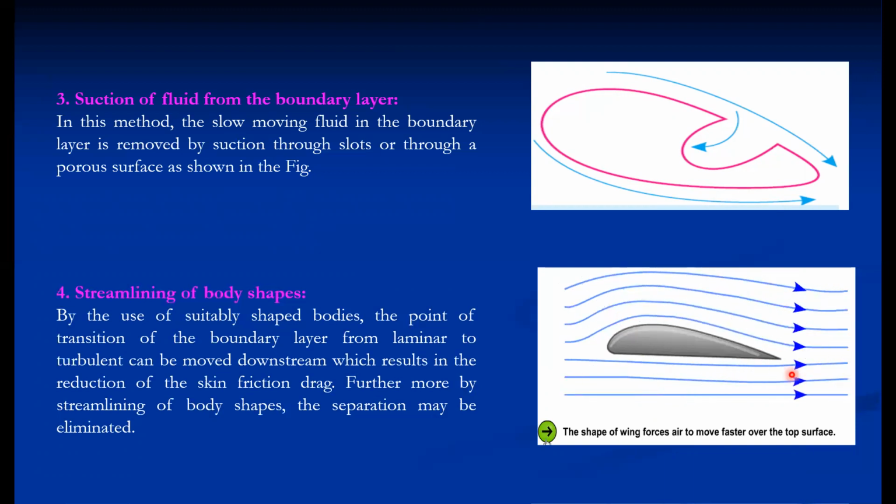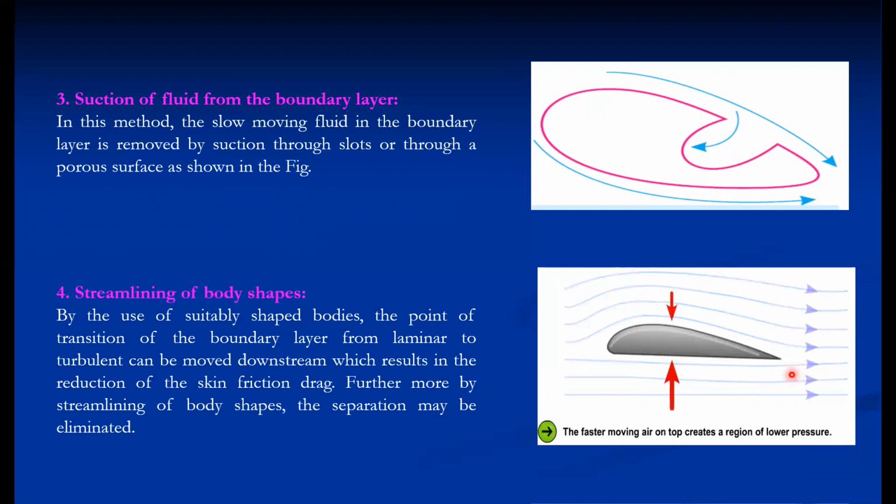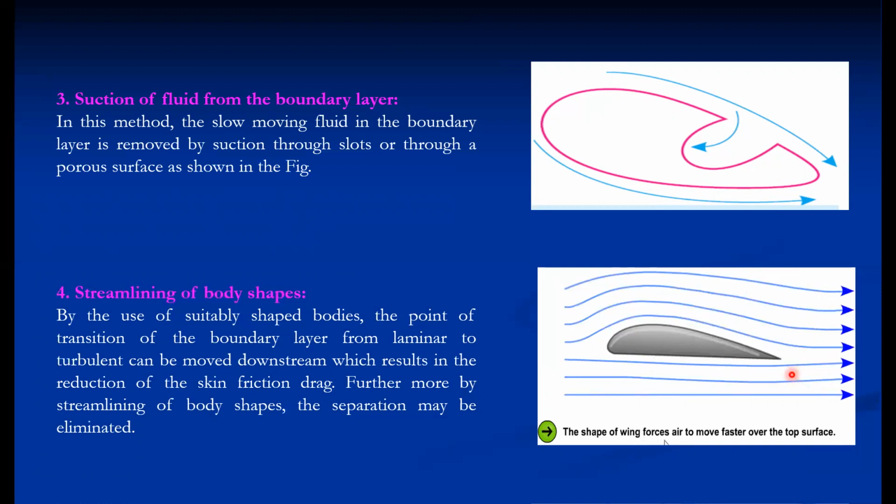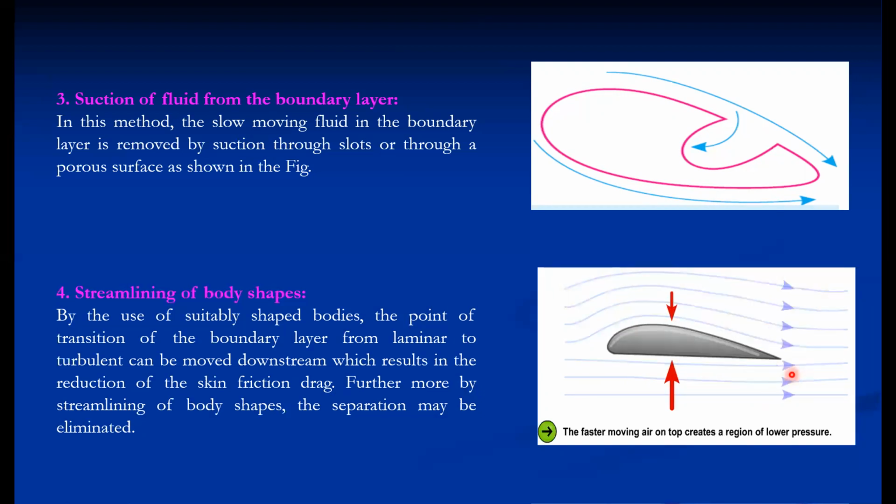These are some techniques where we can eliminate the separation completely, or we can prolong the separation so that the total drag force can be minimized. Because the separation causes an opposite force on the downstream. So it further reduces the motion of that particular fluid. So that's why, even if we prolong the separation, the wake region decreases considerably.